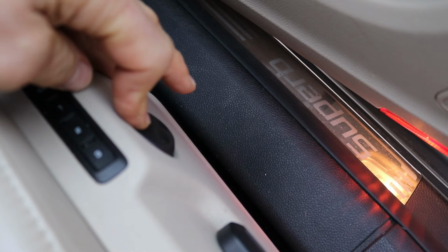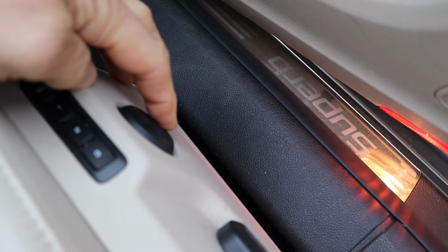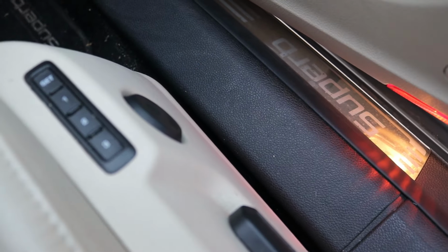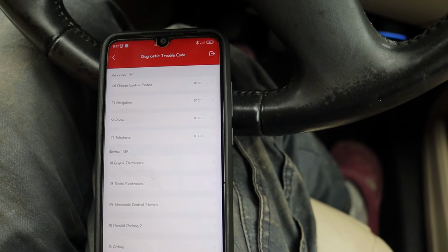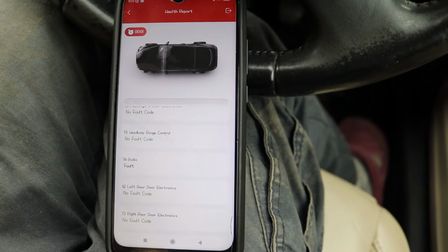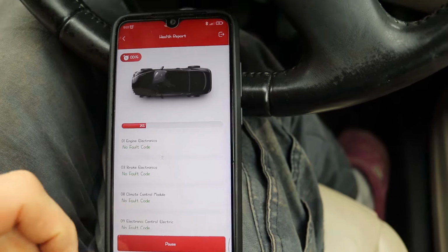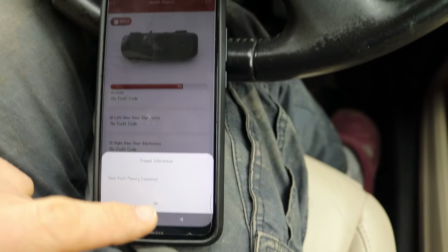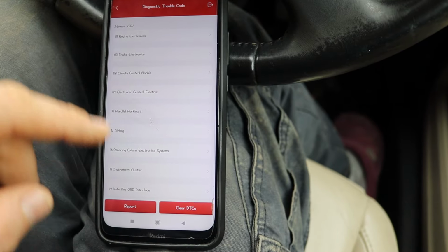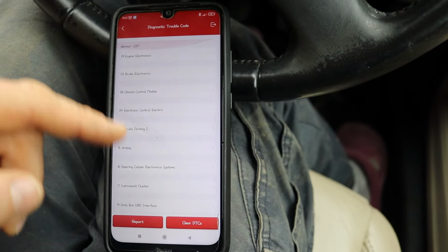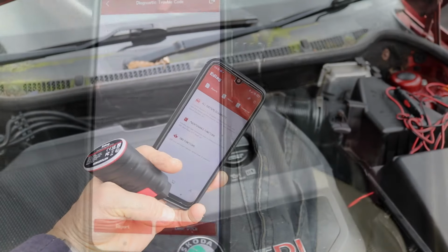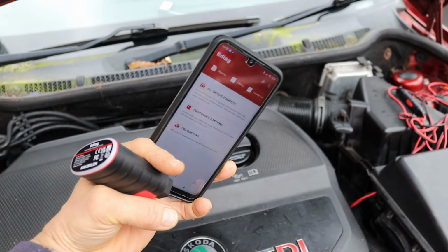And that seems to be working. I can hear the motor and I can feel the lumbar support moving. So I'll clear that. Tell you what, I'll just clear all the fault codes and see what happens. There we go, all clear, non-persisting. Probably just my battery voltage was a bit low, as it does recommend that you have over 11 volts to do the test anyway, so I'm not worried about those.